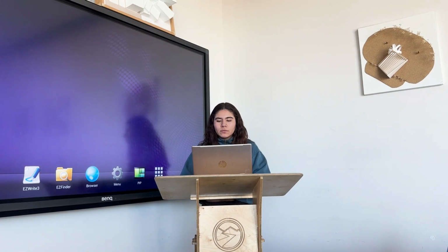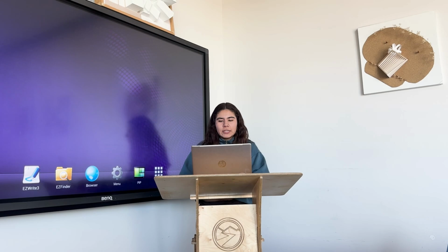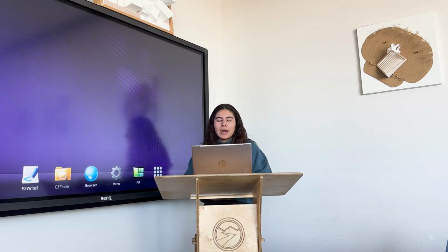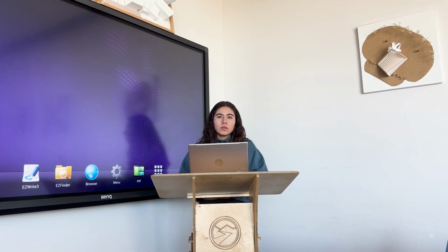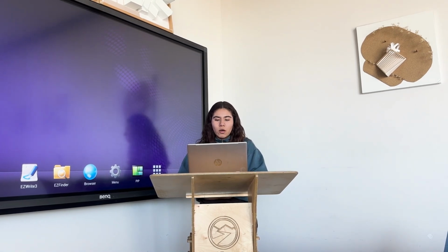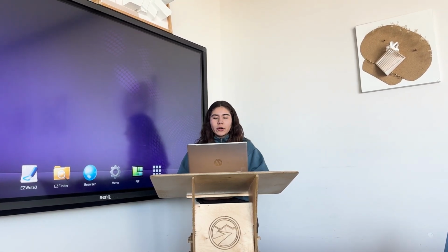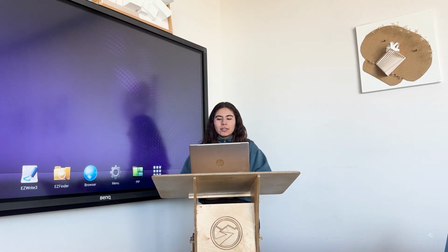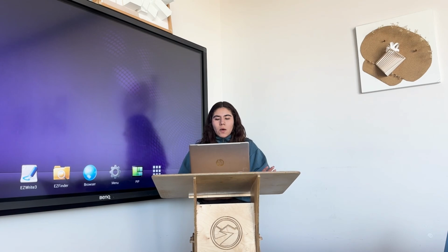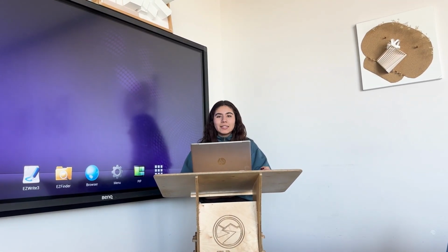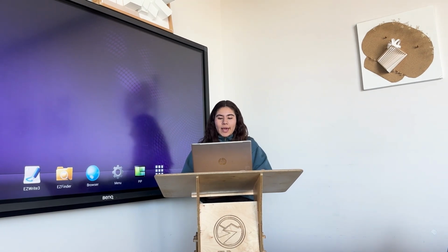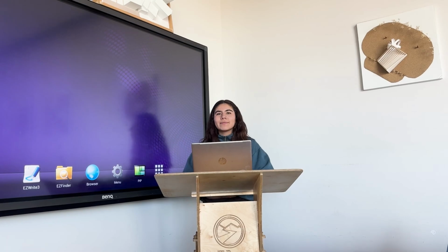So the joint reinforcing must be interrupted at movement joints so that it doesn't restrain the opening or closing of the joint. To prevent out-of-plane displacements of the wall, various kinds of vertically interlocking details may be used. Most movement joints in masonry walls are closed with flexible sealants to prevent air and water from passing through.